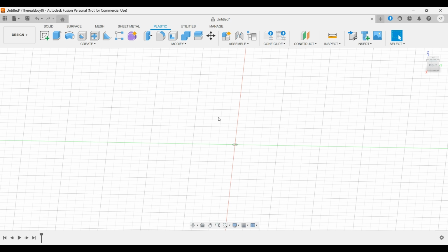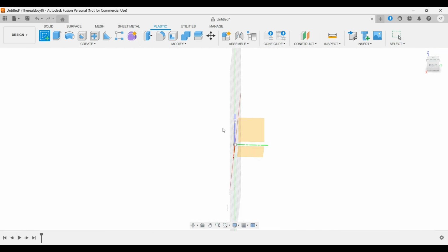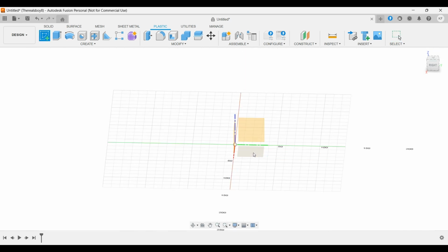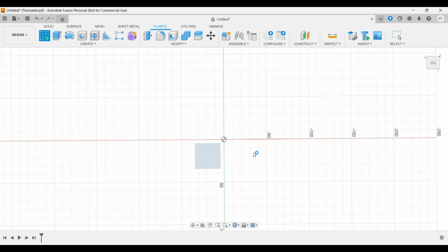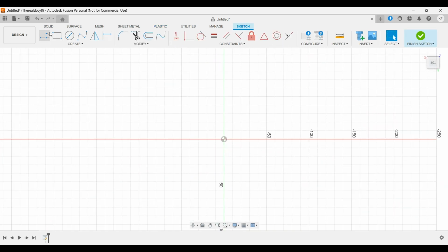Now, how do you make a shape? Because that's what all this 3D modeling is. First, you go to create a sketch. You choose the axis you want it on. So for now, we're going to change the base axis. You can do a line, 2-point rectangle, all these different things. There's a bunch of different shapes, very helpful. And for now, we're just going to go with a 2-point rectangle. And as you move it out, you will see these measurements pop up. Most of the time, they're in millimeters. If you want to change that, you can always go back in settings and do that.